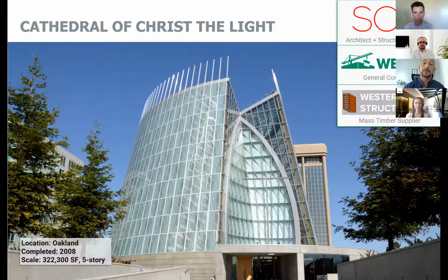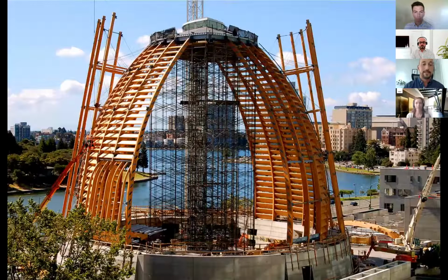The architect and structural engineer were SOM. Webcor was the GC, and Western Wood Structures was the mass timber supplier. You can really see in this photo that it's an 18-foot reinforced concrete substructure with glulam members that are tension supported with structural steel rods.